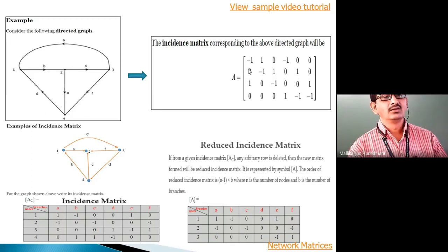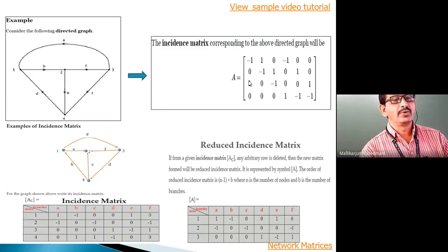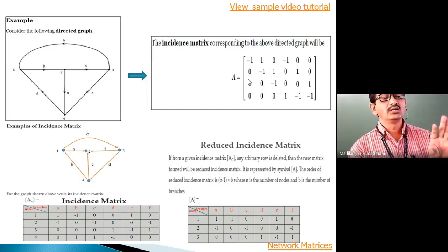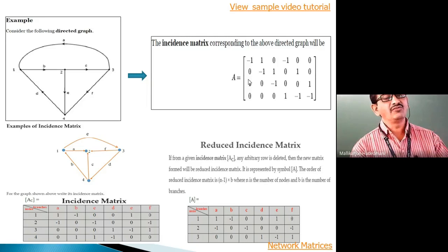No matter, usually our problems will be of the nature that the number of buses will be lesser and the number of elements usually larger by count. This is your hint. The larger count side can be treated as elements, the lesser count is usually buses. If there is still a conflict, you can use the rule of Aij to justify it.